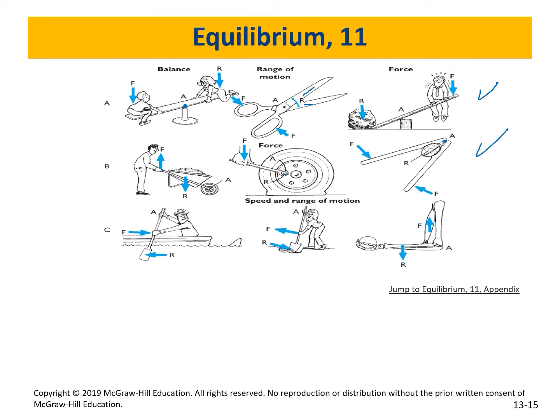Class 3, the force is in the middle, right? So here we have the resistance, the force you're pulling, and you're trying to rotate around this point, correct? Here again, that's resistance. You're pulling up, and then you're trying to rotate it this way. And now for muscles, for the body, this is your center of rotation. That's the force pulling up, and this is the weight pulling down. So the force is between the center of rotation and the resistance. Does it make sense? So that's class 3.